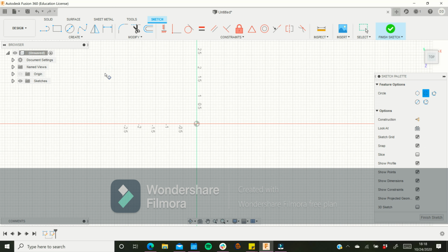Let's go 3-point circle. This one's similar, except this time you're going to drag over here, and then you're going to drag it to make your 3rd point. So the first 2 points are just 2 points that are always going to be touching your circle no matter what. And you can drag this other point here to set your diameter and sort of the position of your circle.